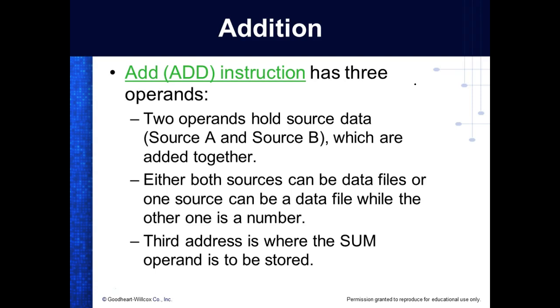So we can address these two data files directly. I can take the contents of the input port, Input:0, that would take word 0, and then I could add it to another number and come up with an answer. And what could I do with my answer? I could store it in an output port. So we can put anything in those output data files we want to. And that's one of the reasons we can force things, right?